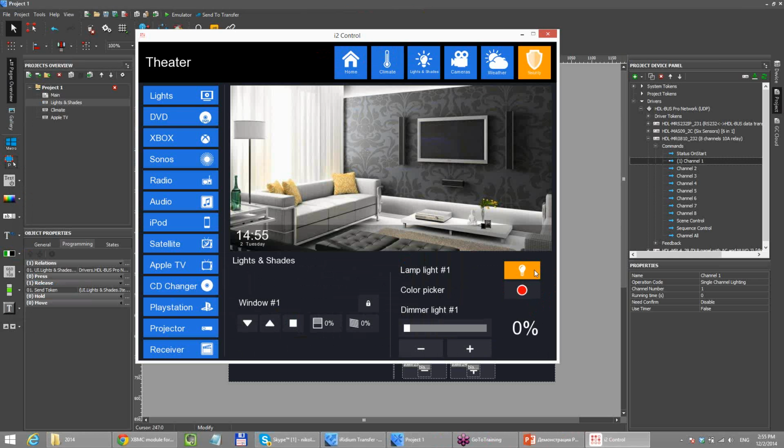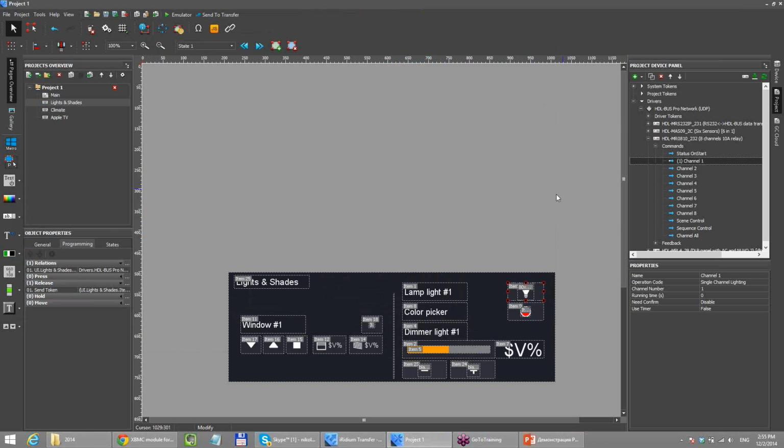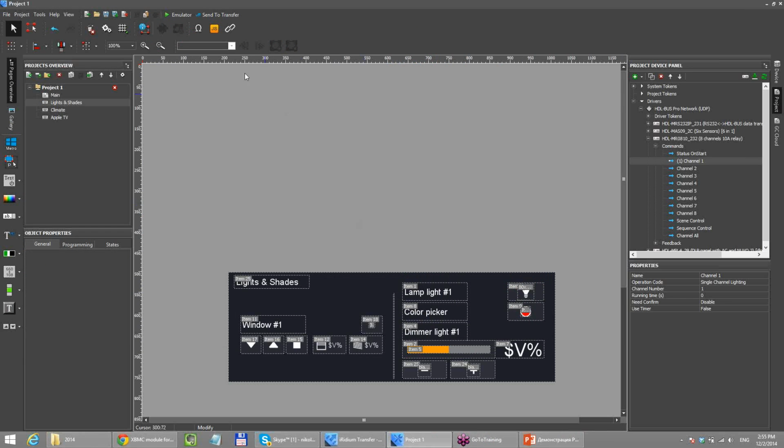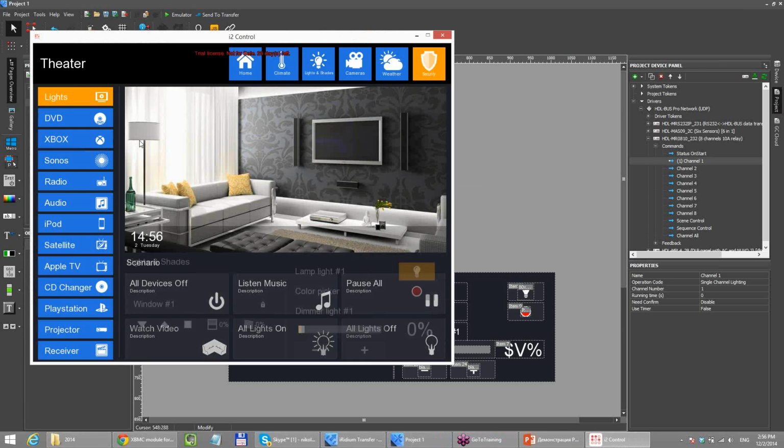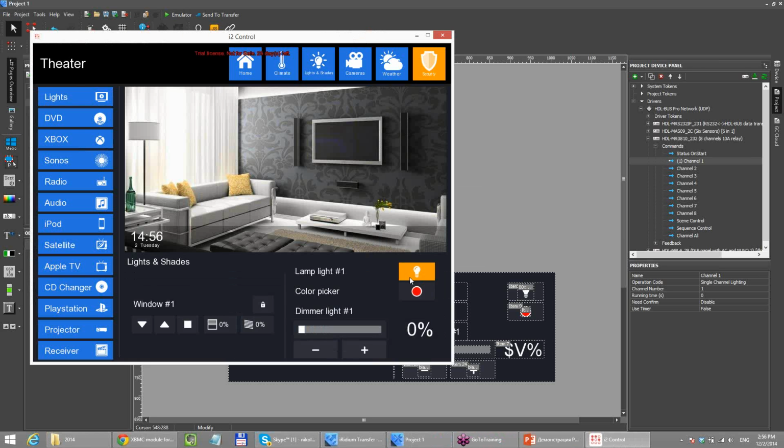You can see that it, maybe you do not see, but you can hear it, that it gives you nothing. First time it turned off, but when I try to turn it on, no sound. Yeah, relay is not on. Why? Because this button is, let's go to general, is trigger button, but it sends 0, 1, and relay only understands 0, 100. So I change it to 100 and try again. Now it works.